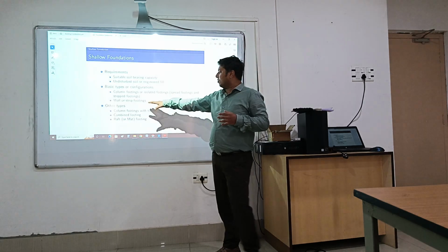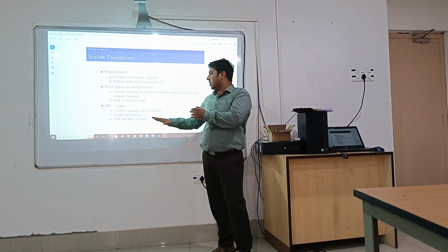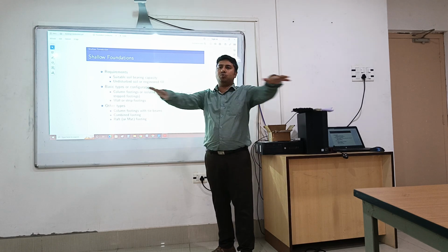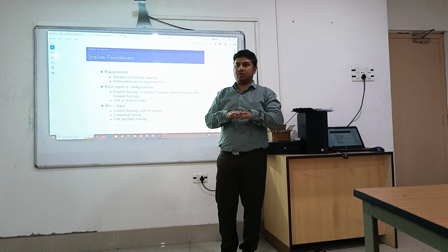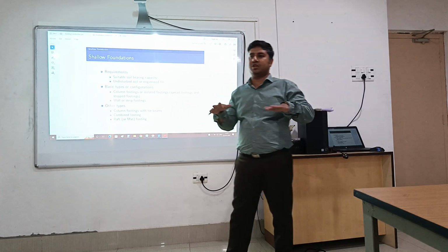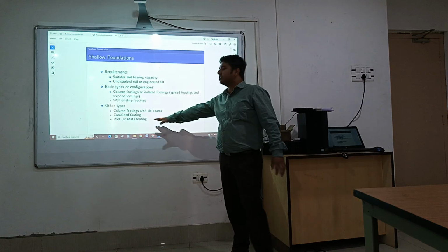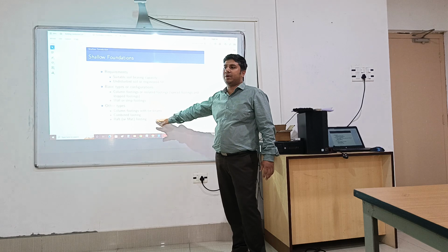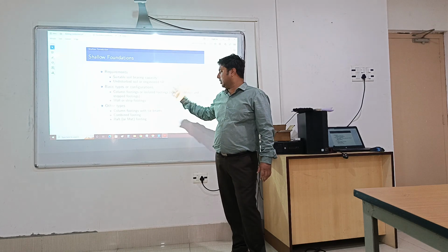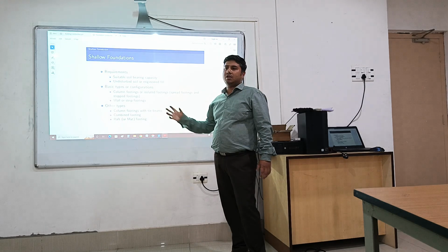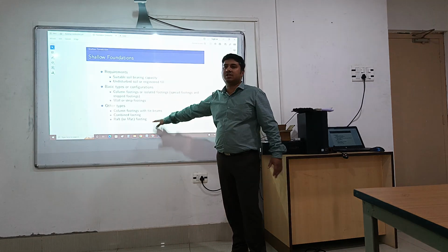In wall footing, a single span will be connected together, but in the raft footing, the bottom throughout the structure will be connected together. There will be a slab type structure connected with every foundation. So this is how it is more stable. A raft foundation is able to take more load, and it also utilizes less space. If adjacent space is not available, then you may use this raft or mat footing.